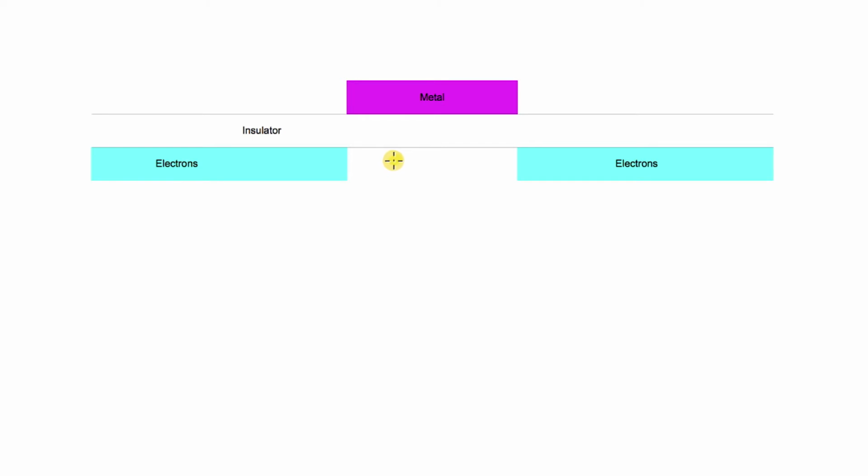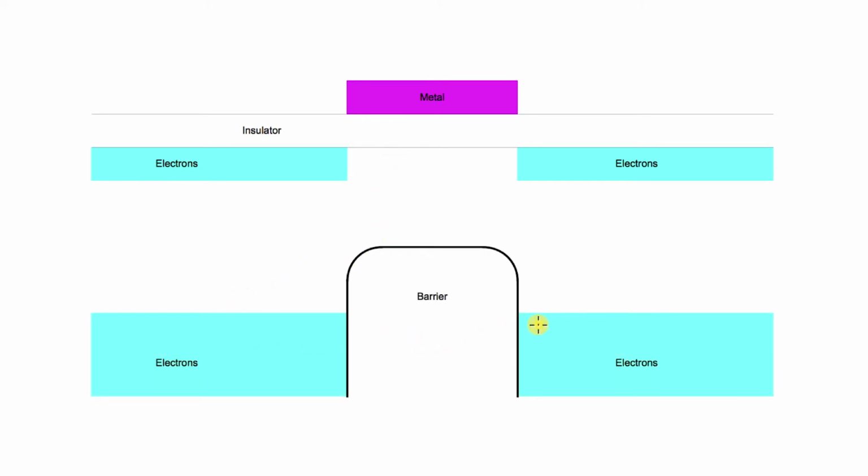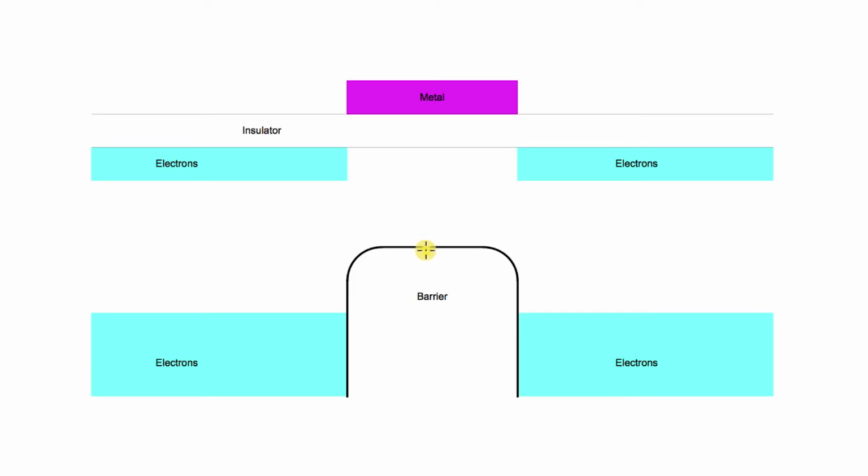So we've plotted down here in the lower plot the energy of an electron right at the surface between the silicon itself and the silicon oxide. And what we see is, because the electrons are so much happier here with their donor atoms, when they try to get out into the silicon between those regions, there's an energy barrier. They don't have all those nice positive charges to keep them happy. So it costs energy for them to get out there, which means if you have one of these regions with electrons in it, it's effectively disconnected from another such region, even if they're close together.